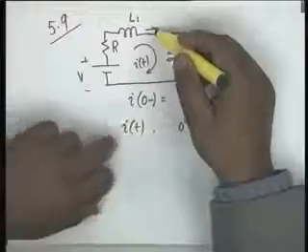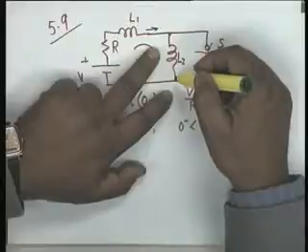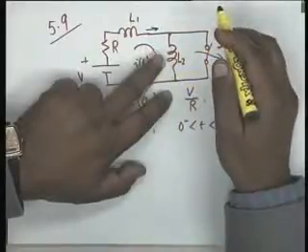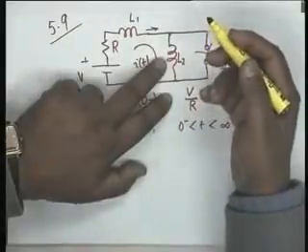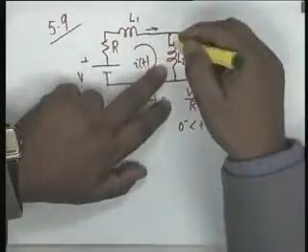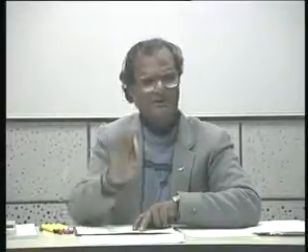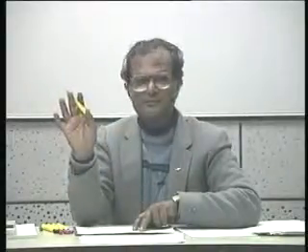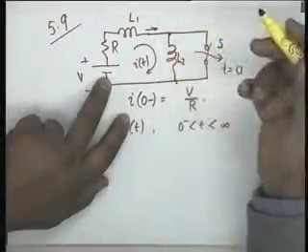This current after coming here, when this is short, this is also a short, L2 is also a short. Initially, it's an open circuit at t minus infinity, but that doesn't matter. The current cannot be established, but whatever current will be there, that will be discharged. Who will oppose it? Once the current has been established, this has become steady. You agreed that the steady state current is V by R. Okay, the current is steady, there is no di/dt. So the voltage across this shall be 0. If the voltage is 0, obviously it is a short circuit.